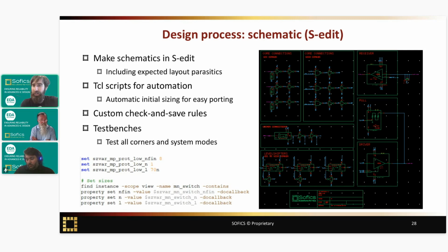An LDO implementation is quite typical, yes, but we are definitely looking into other implementations as well, because one downside of an LDO implementation is that it is very good at delivering current in one direction, but if some current were pumped into this supply rail in the other direction, an LDO is not good at handling this. So absolutely, looking into other biasing strategies is a good idea.